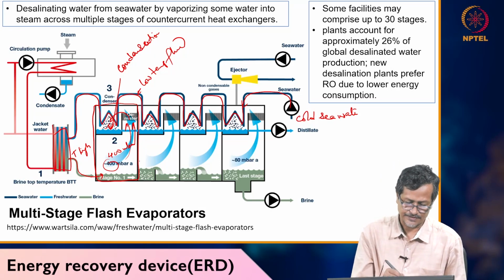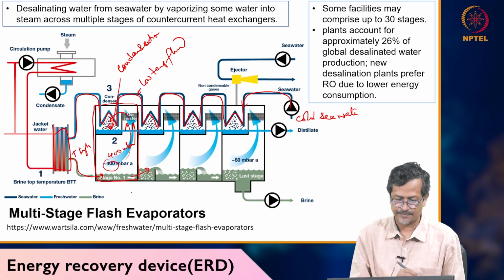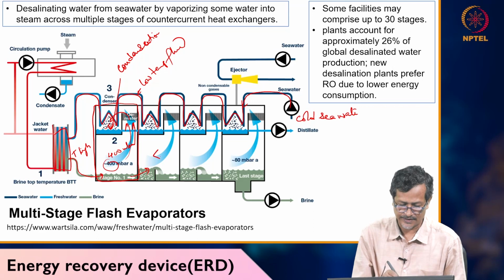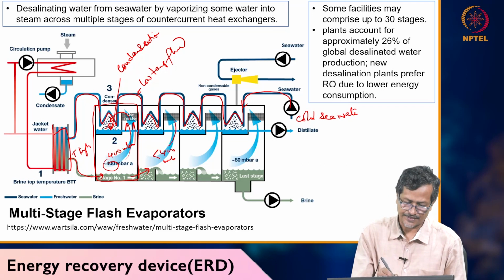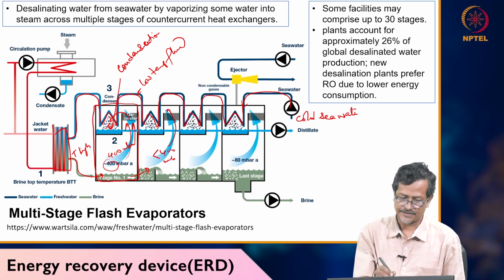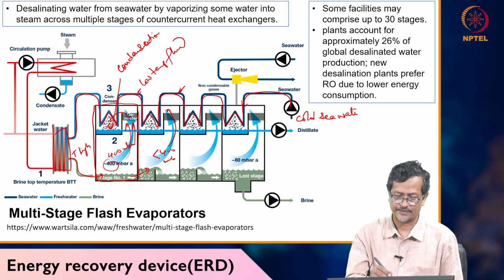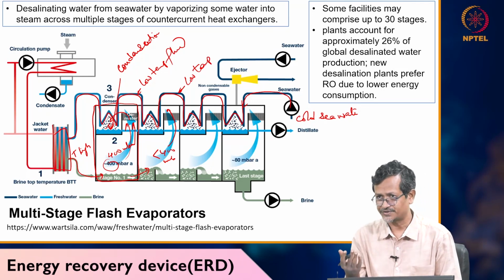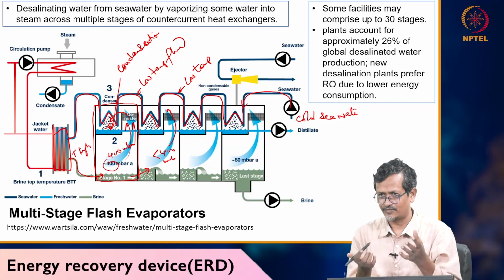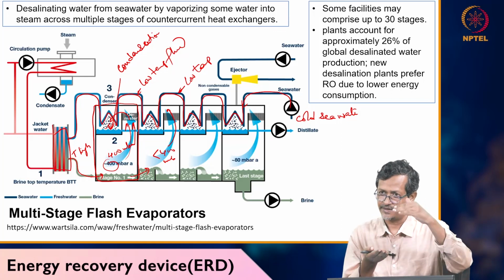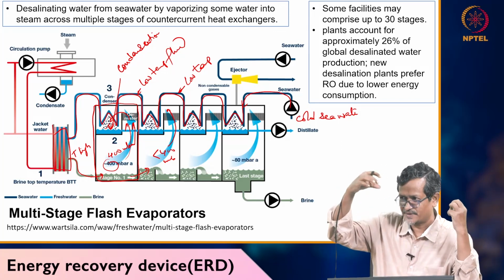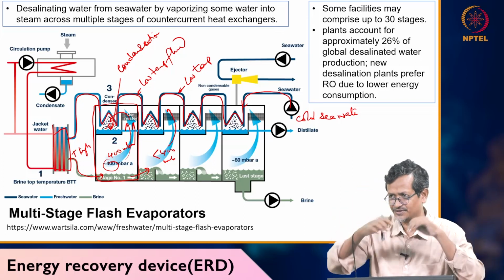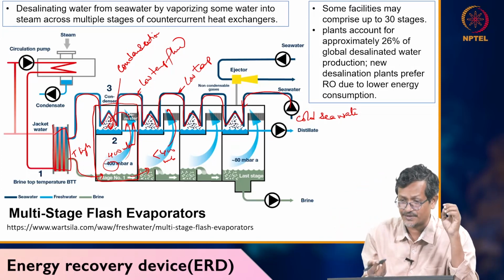So, you got certain filtered water. Now, this water will go further to this chamber, where pressure will be further lower, less than 400 millibar, but still it will give up a certain amount of vapor, because this seawater pipe is a low temperature pipe, and pressure will be lower. Because of lower pressure, again a certain amount of vapor you are getting from the water surface. If you are reducing pressure, you are getting more vapor. So, when vapor goes to the top, the cold pipe is there, and the cold pipe will reduce temperature, and you are getting condensed water.